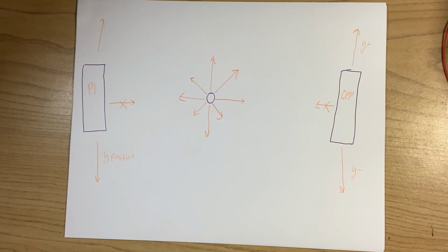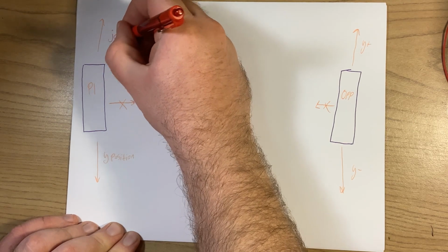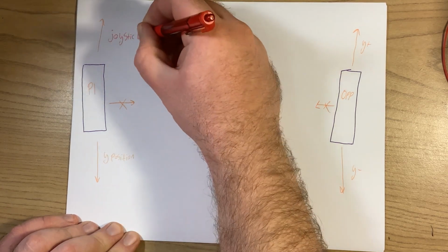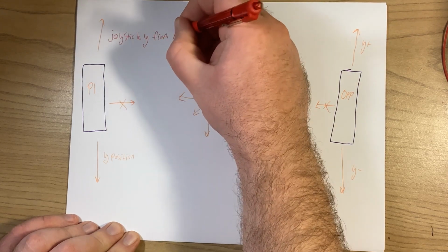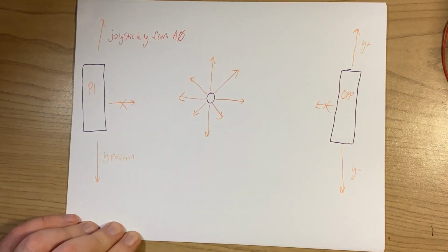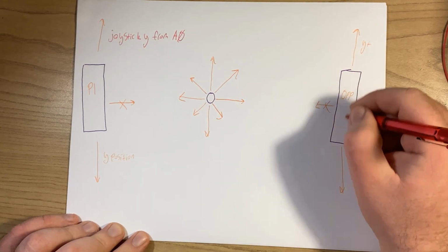I know we plugged in a port for our X on our joystick, but honestly, we won't need it. All we need is the joystick Y value. I believe that was from analog 0.